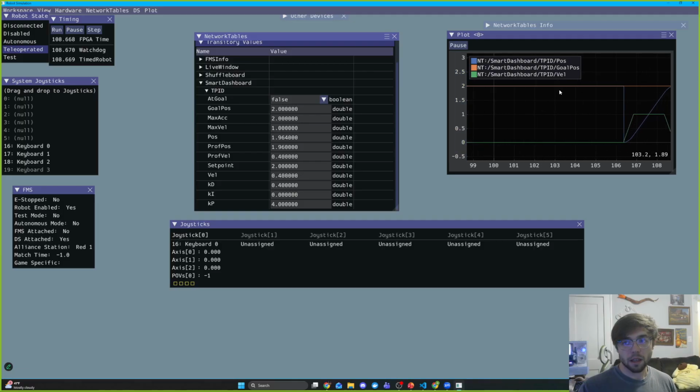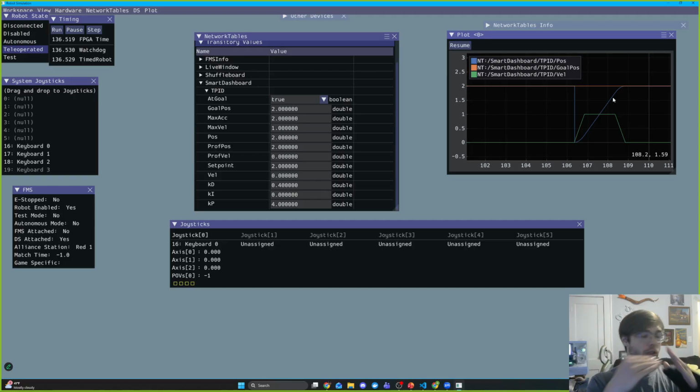So what it looks like is we've got our velocity, which shoots up at the start, so we've got good acceleration, but we hit our maximum velocity of 1, so we're just cruising until we get to this point where we're pretty close, so then we start decelerating. And so what that shows you is you've got that nice acceleration at the beginning, which gets you up to speed, but then you also start slowing down when you reach your target so you don't overshoot, right? So the odds of overshooting with these are much smaller.